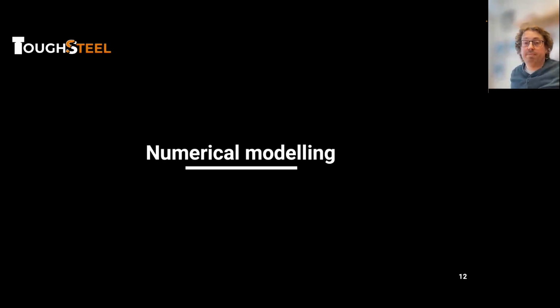But this method is of course still interesting because we can validate finite element simulations, and we can extract the maximum amount of information. Since we have a calibrated 3D digital image setup, the experiment can be further used to validate finite element models. Because of course, to promote the use of these new materials, accurate finite element models are needed. It's easier and cheaper to test new designs virtually than creating prototypes and tests.